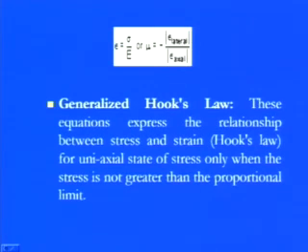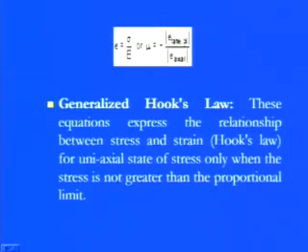Whatever deformation there is, it is based on the isotropy and homogeneity, because if it is not exactly equal in all directions, then it will exhibit a Poisson ratio with a different meaning for minus epsilon lateral: the deformation in the x direction and the deformation in the other mutually perpendicular direction, irrespective of y or z. So this discussion of the homogeneous or isotropic part is exactly similar to this kind of